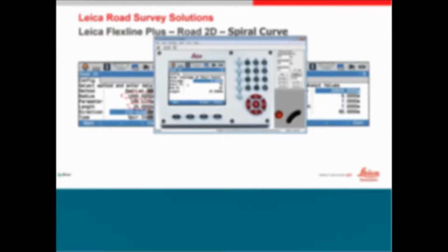You have to define the starting point chainage. It can be any chainage that follows your drawing, and then you choose stick or check. Check means that you just measure any point, and it tells you the offset and the chainage of that point. Stick means that you want to stick a particular chainage and particular offset, for example chainage 110 and offset 2 meters or 3 meters. You can use the stack to do the stick up.